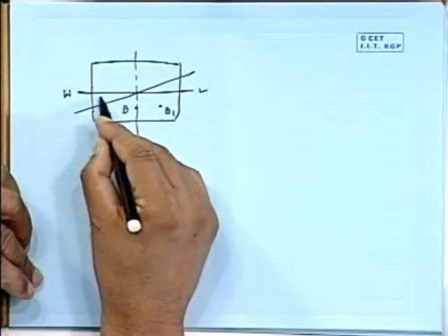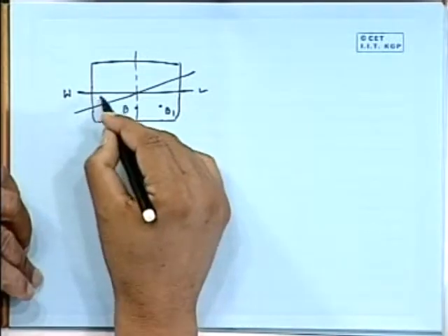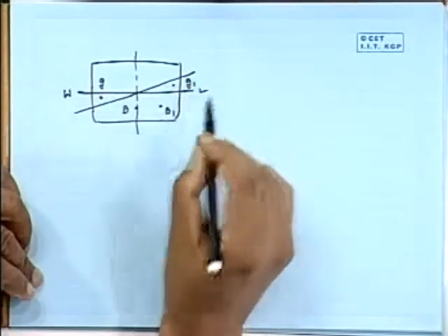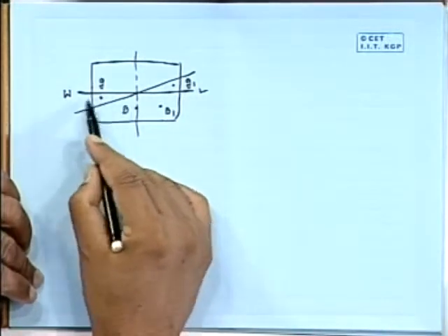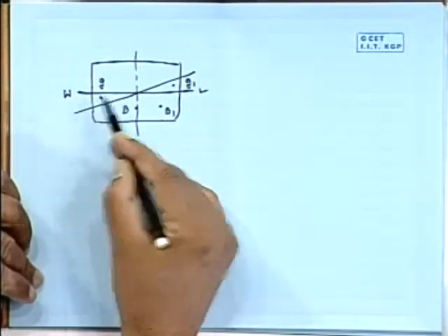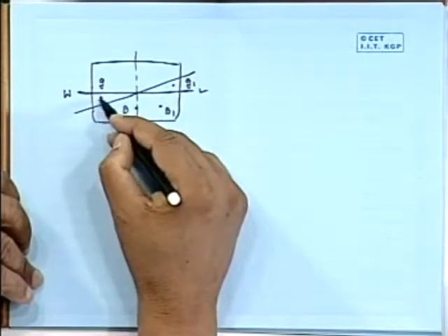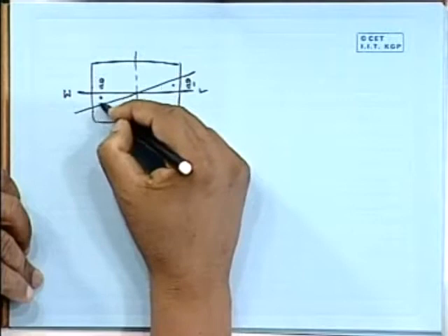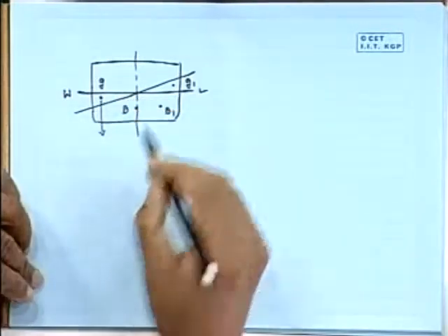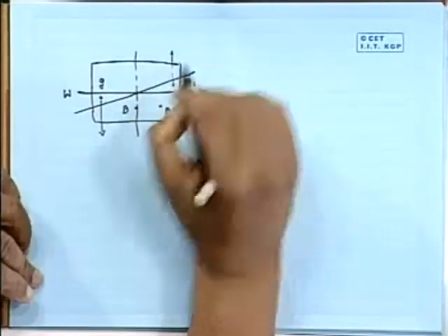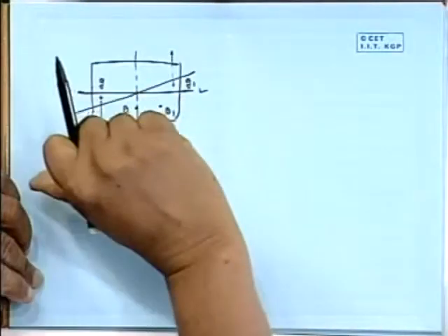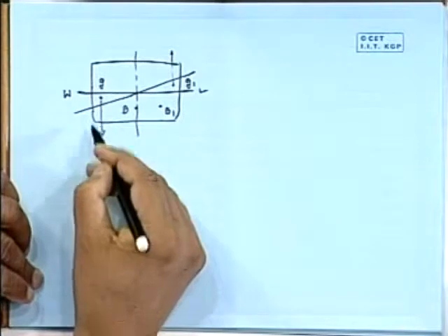Remember that here I had a centroid of this location, say G here, and this centroid is G1. It is something like I have cut this piece of cake and added it here. That means I have removed this buoyancy force which was there, which is otherwise acting here. When I cut this off, I am actually adding a downward buoyancy force, because this was giving me upward buoyancy force.